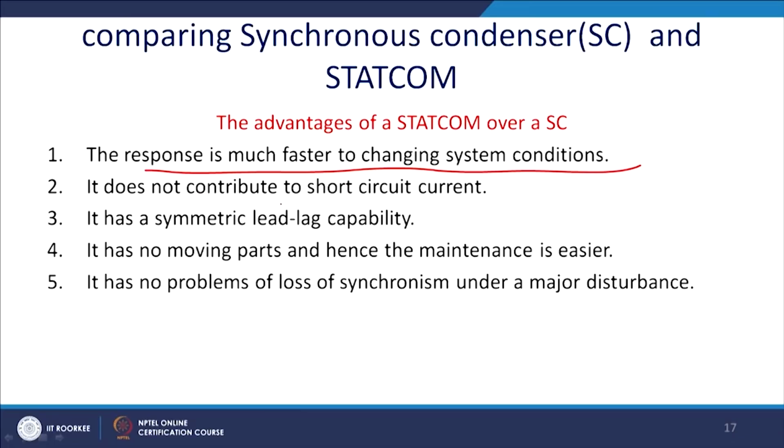It does not contribute to the short circuit current. It has a symmetric lead and lag capability, so both are symmetrical in nature. It has no moving part, and thus maintenance is easier, and we can put in redundancy by adding only extra legs or something like that, so that you have more reliability.